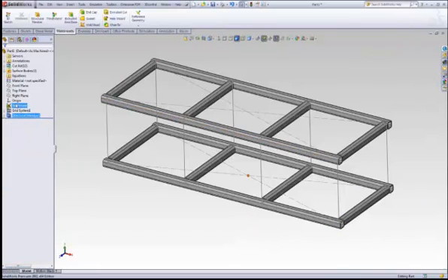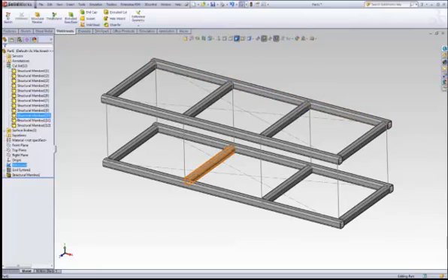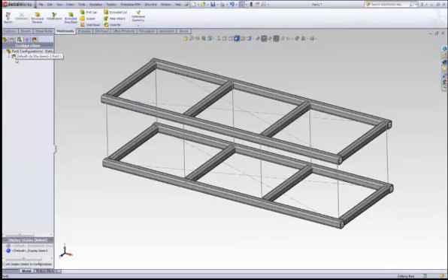Also, you'll notice that this weldment feature came in, and this does a few things. First, it changes your solid body folder to a cut list folder. And if I expand this, you'll notice here are all those solid bodies that it had generated. It also, under your Configuration Manager, adds a configuration. See, we've got Default as Machined and Default as Welded. So if you do have any machine features, you can go ahead and suppress those in this nested welded configuration.